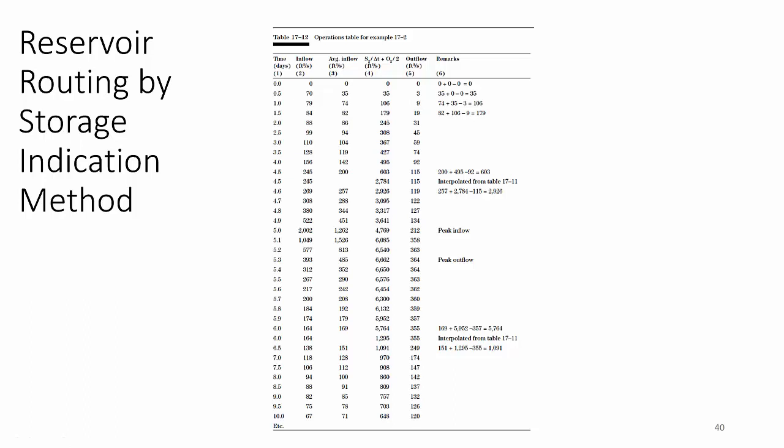And so we just keep ratcheting down our lists and interpolating to the extent that we have to, and that's the way we create the outflow hydrograph. Now, it seems convoluted because it's a time step forward filling in a back time. That's because it's mass balance based with an understanding that what's stored in the watershed for this time interval will come out of the watershed next time interval. And that's why you calculate forward.